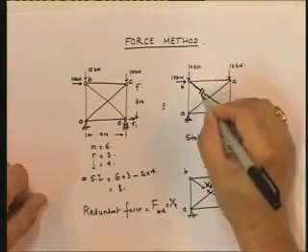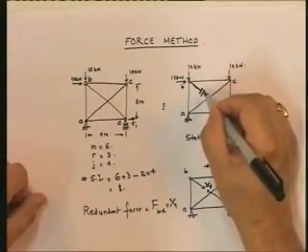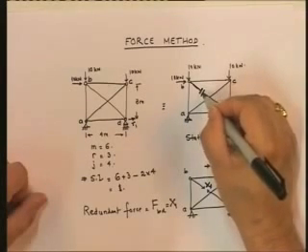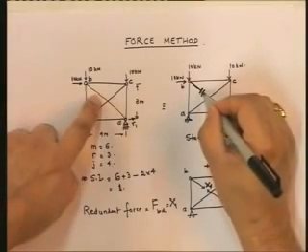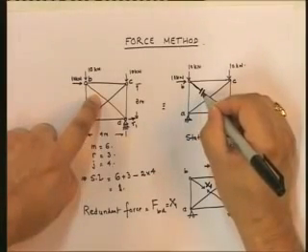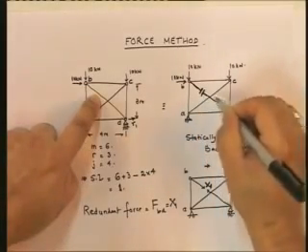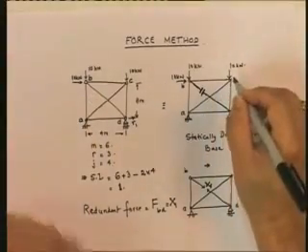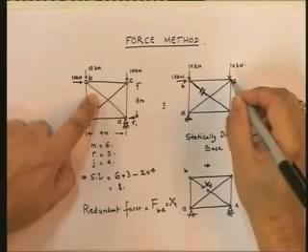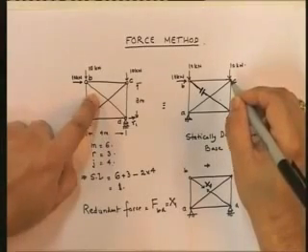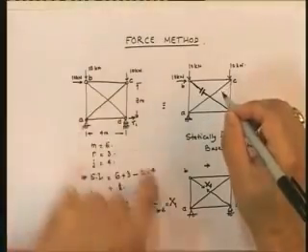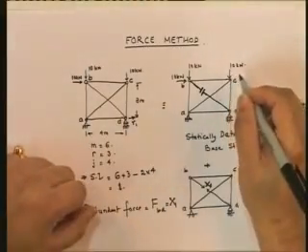But the major point is that once I have made a cut, these 2 points which in the real structure are the same point, and I let the structure deform, are going to get separated. Does that happen in the real structure? No. In the real structure, any point over here is not going to separate. So what's going to happen?